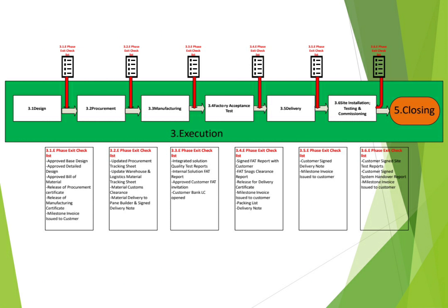Once your team visits the site, they need to ensure safety, and they need to ensure that the site acceptance test report is already approved by your customer. They need to sign the necessary test reports so that all the necessary quality documents are in place. Also, they need to prepare any red markups for any modification happening at the site. After they complete the site installation, testing and commissioning, they need to do the necessary software backups, the as-left settings backup. All of this needs to be in place.